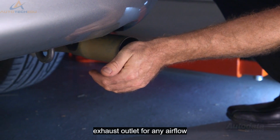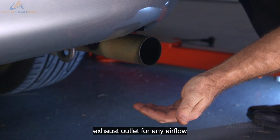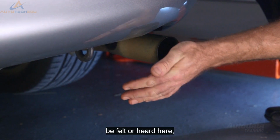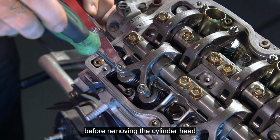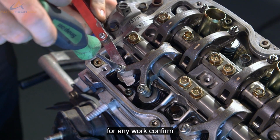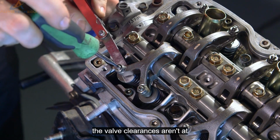Listen closely at the exhaust outlet for any airflow. If air can be felt or heard here, then the fault will lie with the exhaust valves. Before removing the cylinder head for any work, confirm the valve clearances aren't at fault.